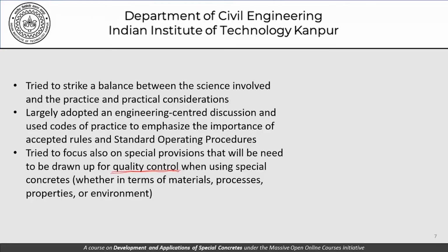That is something which I've tried to emphasize throughout the course. You will recall our discussion that we had in terms of preparing panels for shotcrete in order to get samples which can be used then for determination of compressive strength, or collecting the samples of underwater concrete in a tank of water. So these are the kind of special conditions that need to be incorporated in our testing mechanisms or testing systems, and one should not be afraid of creating new SOPs if the situation so demands.